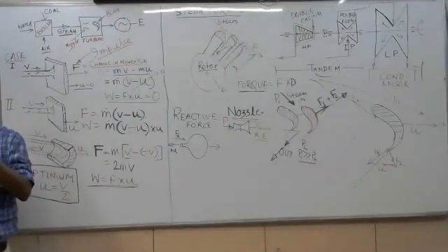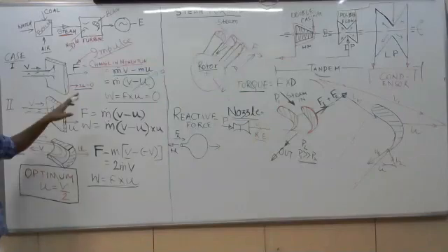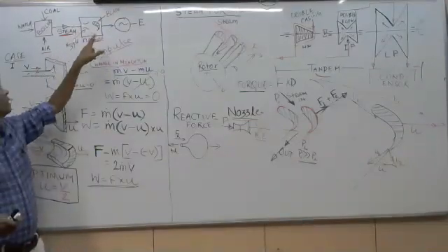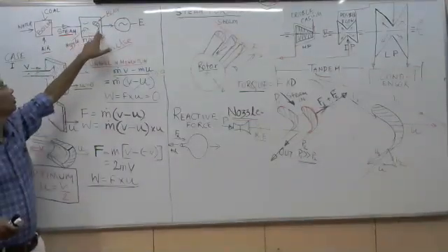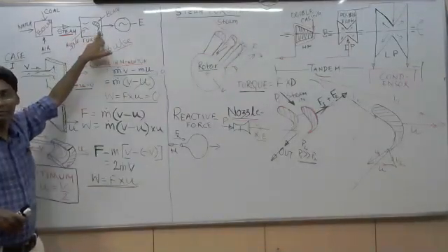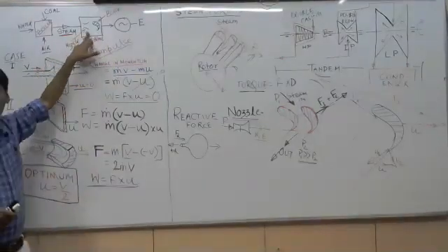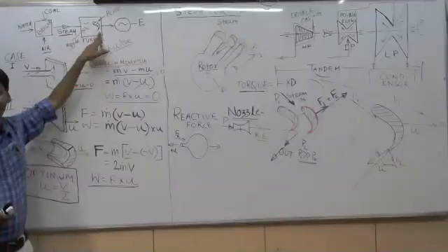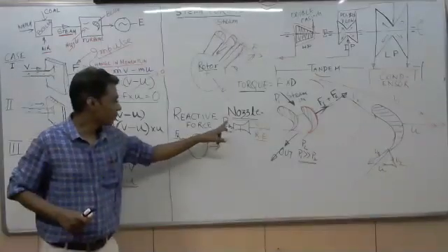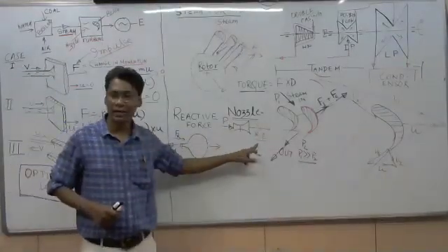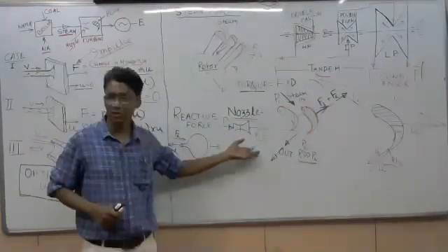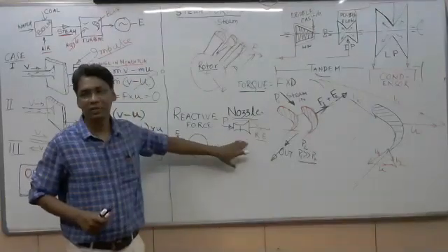The steam contains energy, and we have to extract that energy from the steam in a box that is called the turbine. Mainly, we have two parts in the turbine: one is the nozzle, another is the moving blade. The nozzle is sometimes called the fixed blade. The fundamental function of the nozzle is that it converts pressure energy into kinetic energy. That means high pressure becomes low pressure and we get high velocity steam out of the nozzle. That is the main function of the nozzle.